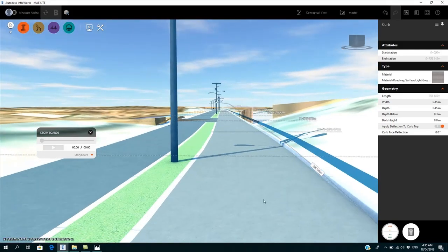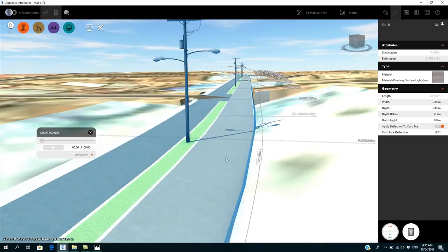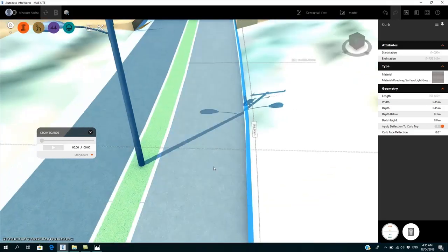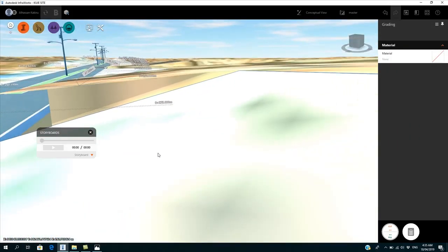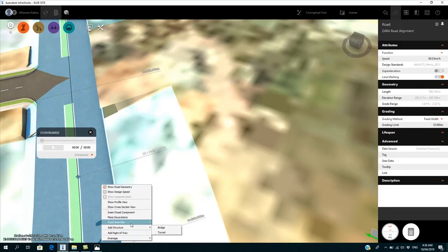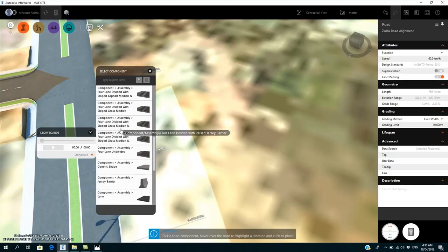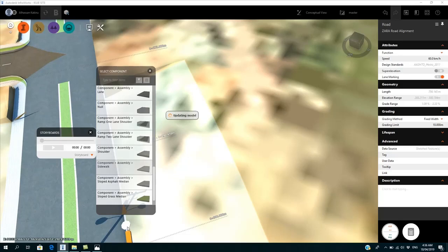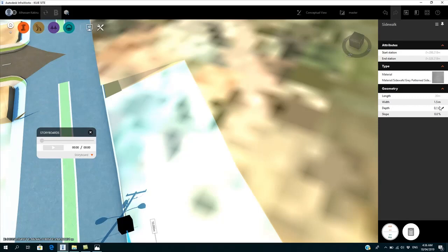The other things we can have within the curb lines is the walkway. So to do the walkway, what we need to do is just select the corridor of the road. This being a single, we have it. Select it. Right click on it. Then we create an insert road component. And the road component we want to start with is a sidewalk, otherwise known as walkway. So the side we want to put it, you show it here. Then you define the parameters for the walkway. Let's say the walkway is 1.2. Then the depth in terms of the pavement is 0.3. Then the slope is 0, 0. Then we as well show the information.